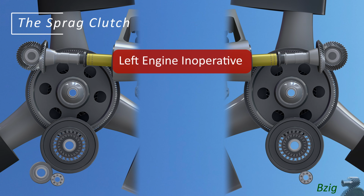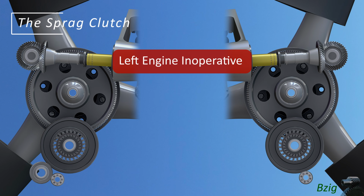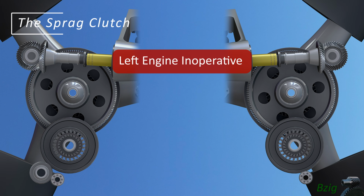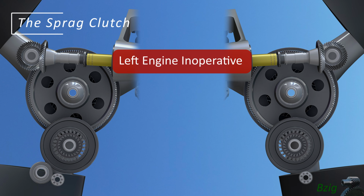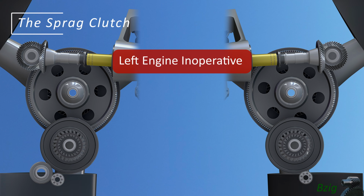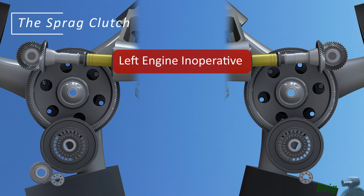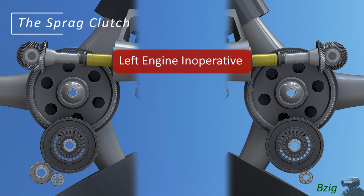In unpowered flight, autorotative forces keep the prop rotors turning, but the engine starts to slow down. As soon as the engine slows down, the inner race becomes a driving component, but the inner race is unable to drive the outer race due to the geometry of the sprags. This is the overrunning position, and this disengages the failed engine and input gears from the drive system.